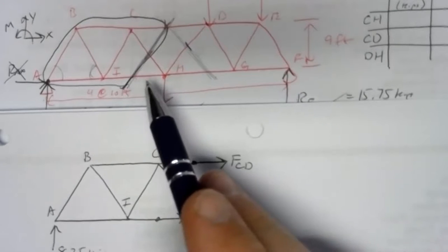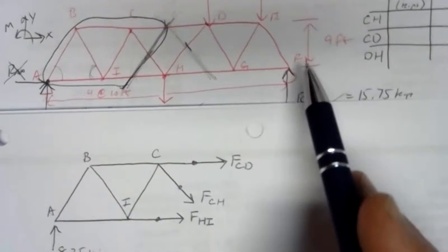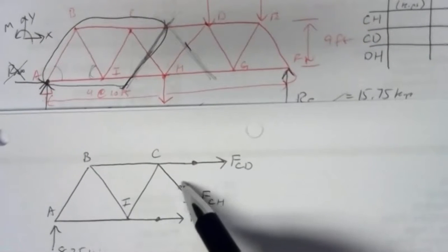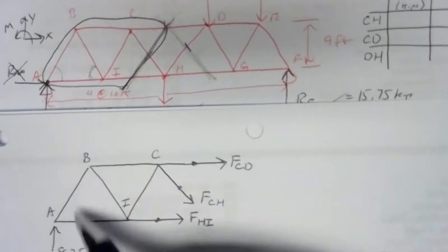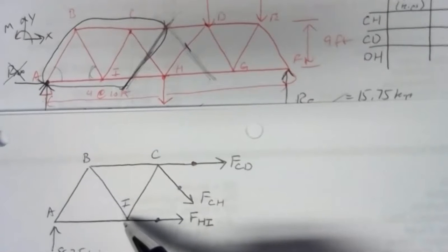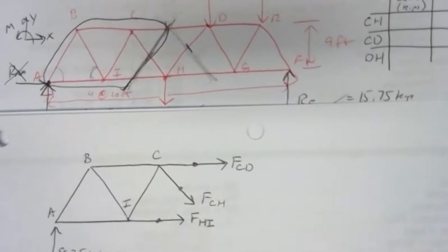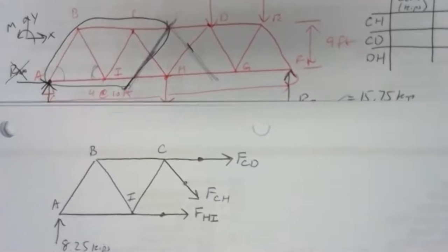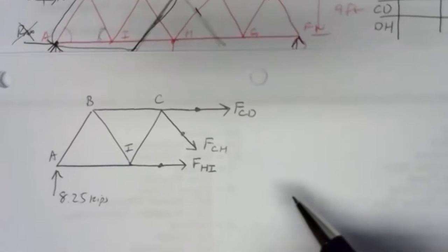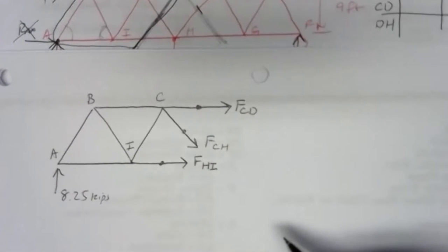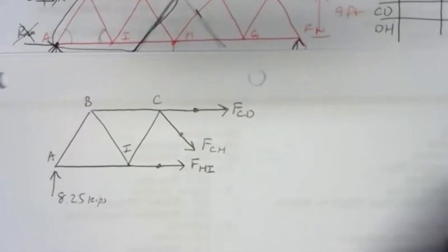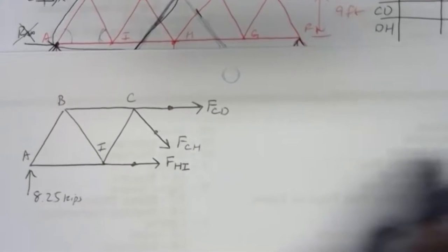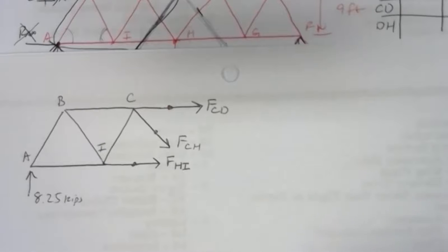So the principle is, if I can throw away this part of the truss, but at that same instant I exactly apply the forces that the rest of the truss used to be applying, nothing will change in the part of the truss that I'm keeping. So we've got the geometry from the problem, and we've got a non-concurrent force problem. So we have our sum of forces in the x direction, sum of forces in the y direction, and sum of moments about a point.